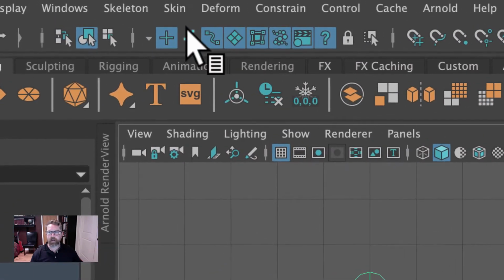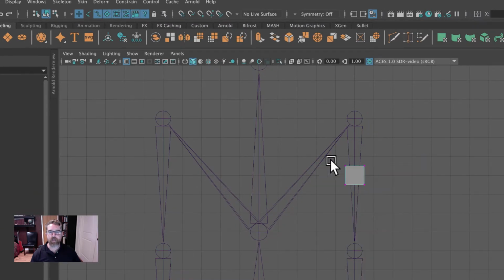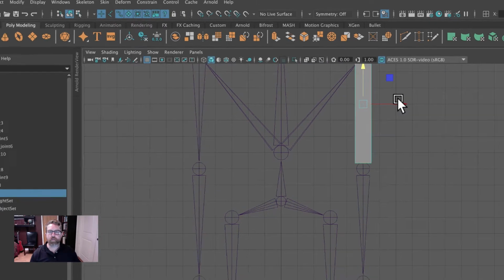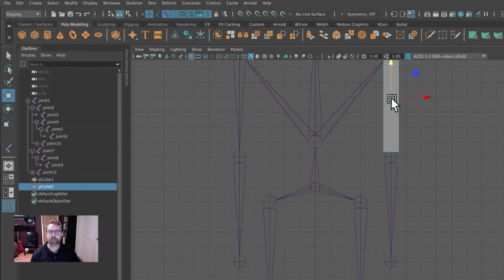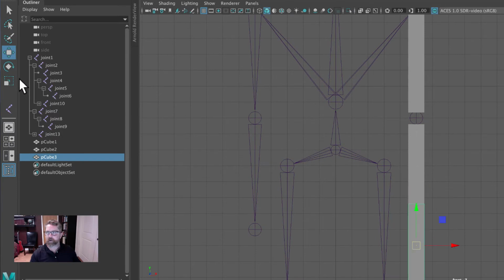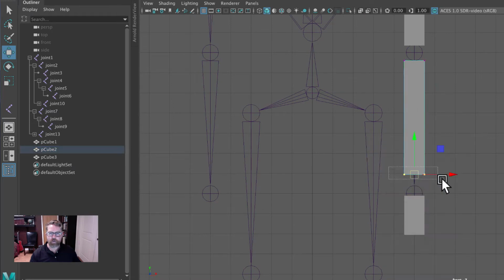But with it masked off, I've got joints masked off here. Now I can just concentrate on selecting the geometry, and we're just going to somewhat arbitrarily pull this up to the shoulder. Now we could put some spheres in here or some cylinders to make it a little bit more interesting, but I'm going to create just a very minimalist version. Right click back to object mode, and we'll just duplicate this, edit duplicate, or you could go to Command D, and we'll grid snap it down. And if that didn't fit right, same idea, you can grab and maybe we'll pull this up a little bit. And then we'll duplicate again, edit, duplicate, and we'll grid snap this down, and we'll make a small cube. I'll just scale it this time. And we want it below that joint there. And I'm going to just pull that down a little bit more.